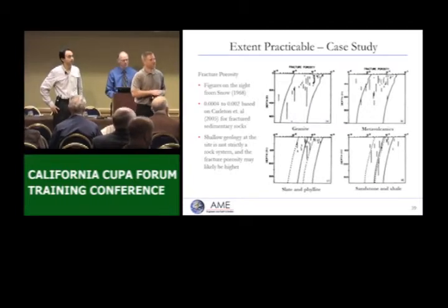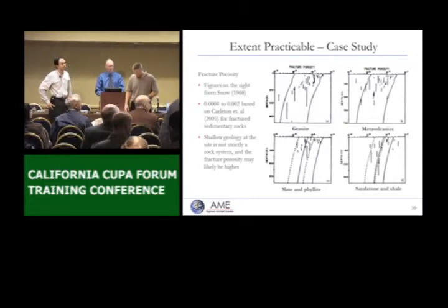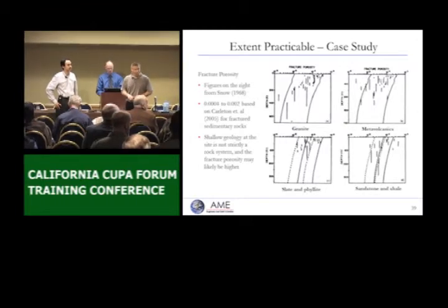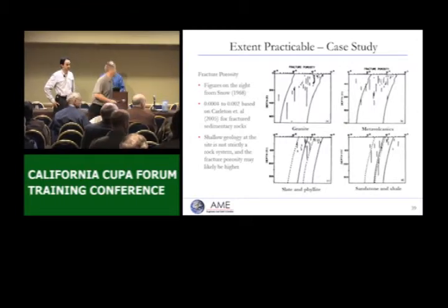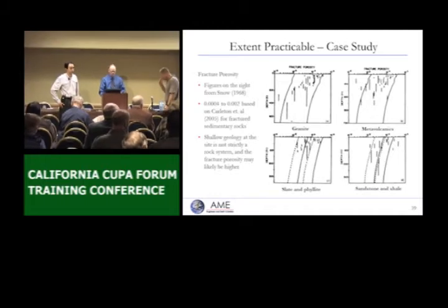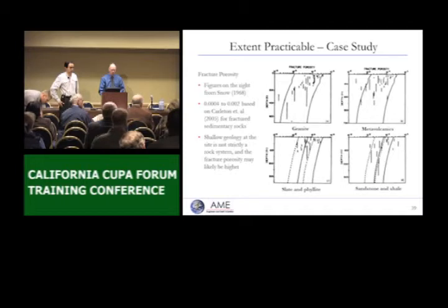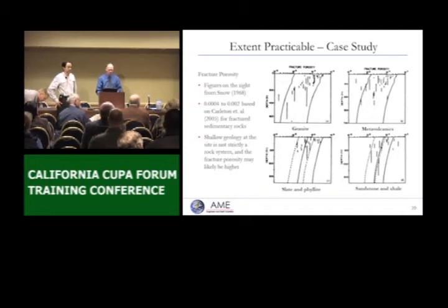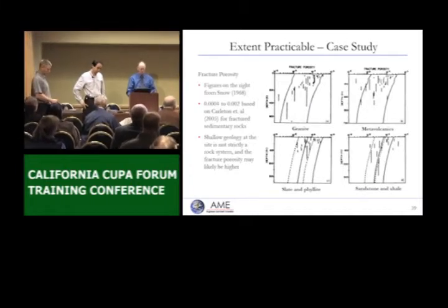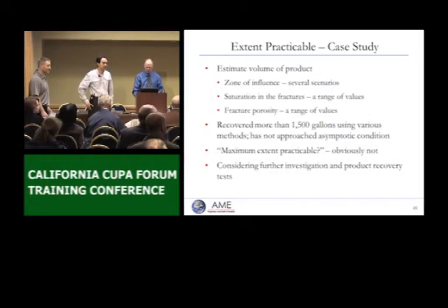Yes. Meng, during your presentation yesterday, you showed a case where there was LNAPL below a confined layer. And when you put a well into that confined layer, you have a much greater apparent thickness in the well because it's under pressure. How do you think that product got below the confining layer in the first place? I have never been able to understand that, because I have seen it in the field too.